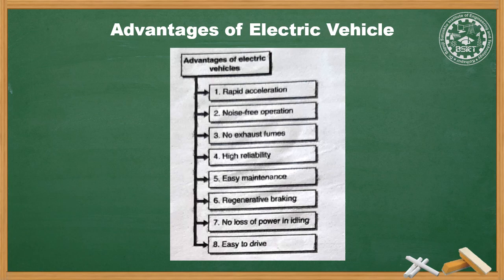The energy loss increases fourfold as the input current is doubled. There is always a compromise between torque and energy efficiency. This limits the top speed of an electric vehicle operating on a single gear, due to the need to limit the required torque and maintain efficiency at low vehicle speeds.